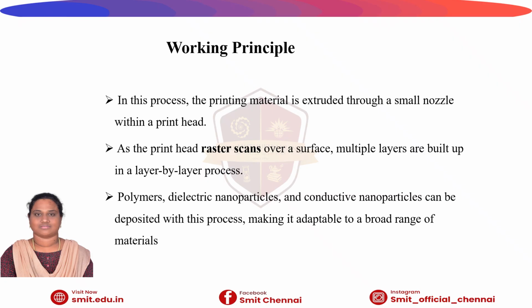Next, we can see about the working principle. In this process, the printing material is jetted as microscopic droplets through a fine nozzle in the print head rather than being extruded continuously. As the print head raster scans across the print bed, material is selectively deposited to form each layer, building the object in a precise layer by layer manner.